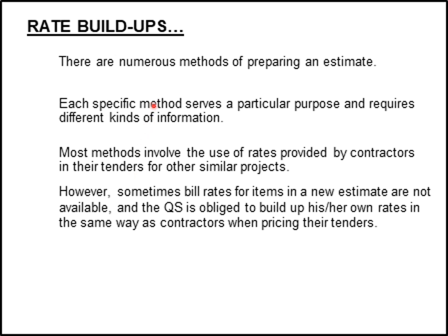There are numerous methods of preparing your estimate. Each specific method serves a particular purpose and requires a different kind of information. Sometimes you will have the information available, sometimes you have to build up your own rates. But most methods involve the use of rates provided by contractors and their tenders for similar projects. So you take your BOQ rates and you transform or translate that into the correct unit.